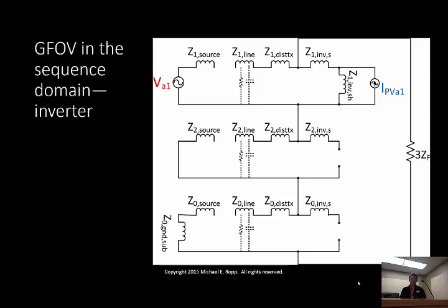When we do symmetrical component formulations in general, we tend to leave out the loads. The reason for that is because usually what we're using this for is we're trying to calculate fault current. The usual source that we're talking about is the utility source. It's the voltage behind impedance. So the fault current is much, much larger than the load current. And by dropping the load impedances, effectively we're dropping out the load's contribution to that fault current, which is okay.